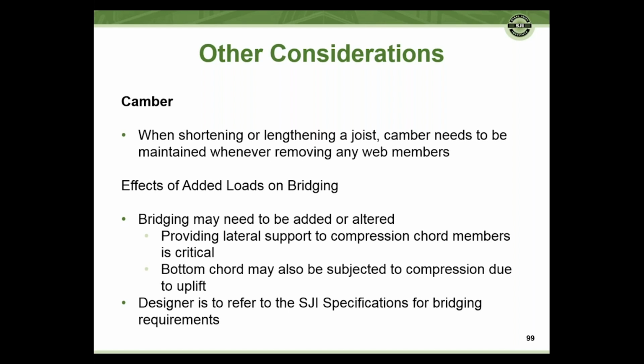If you're adding loads to a joist, it can affect the forces in the bridging and can affect the bridging sizes you may need. So also you may need to add lateral support to the compression chords. That's critical that bridging is there because it does provide lateral support under uplift conditions. Refer to the SJI specs for the bridging requirements. Anytime if you're unsure, the specs can give you some good guidance on bridging requirements.